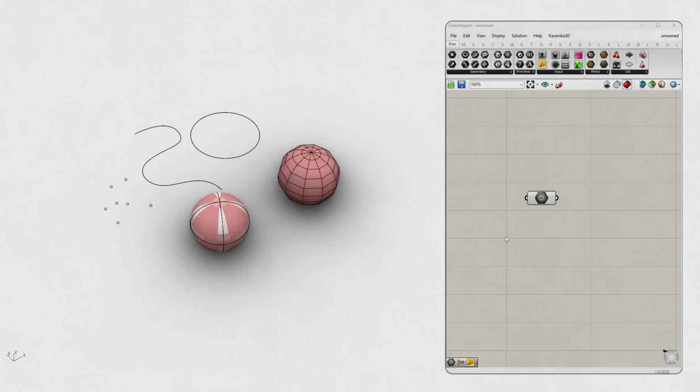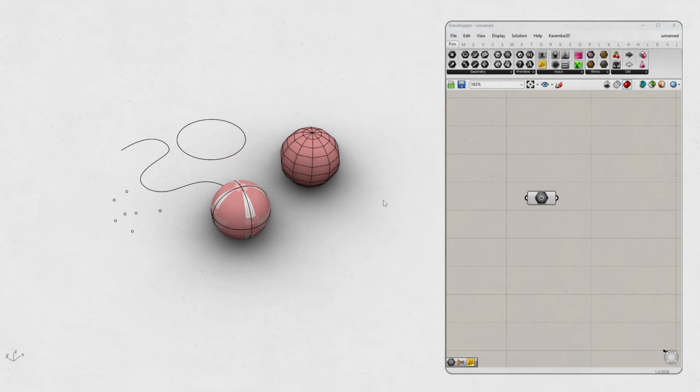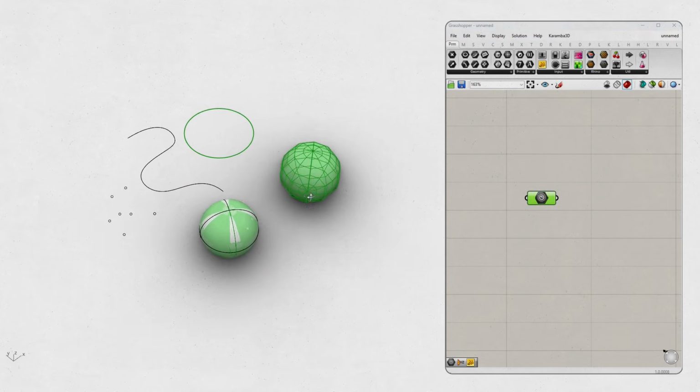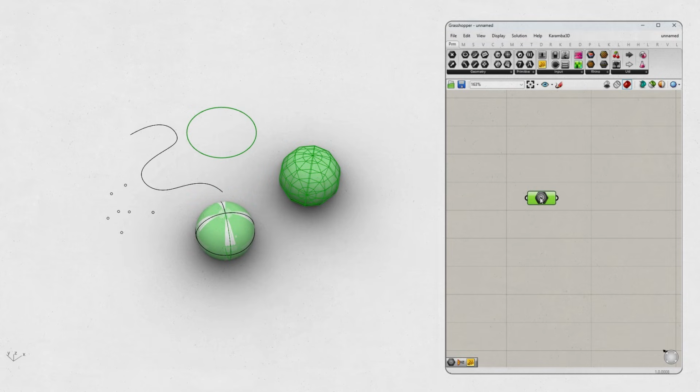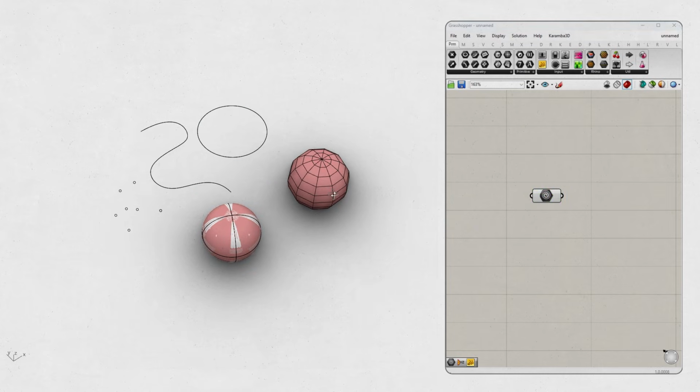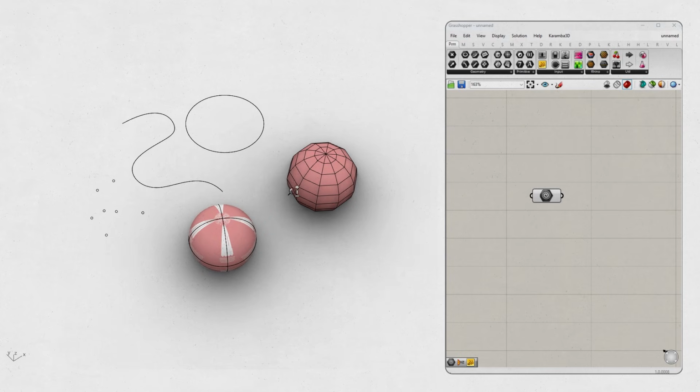It doesn't matter if you're dealing with a point, a line, a curve, a surface, a volume, or even a mesh. It can handle it all. Isn't that wild? So you use this component when the exact type of geometry isn't clear, or when your design needs to accept different types of geometry all at once. It's pretty safe, but honestly, it's way better if you know exactly what kind of geometry you're working with, right?